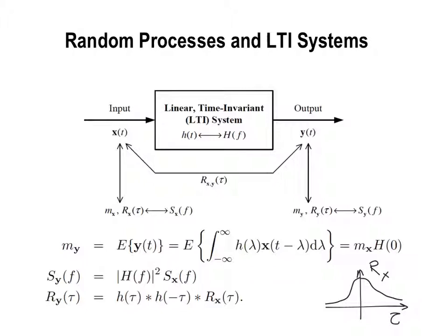You remember when we talked, in the last lecture, about the properties of Rx of tau. We said the peak value is at 0, and then any other value is going to be less than that peak or equal. And if it reaches this value again, it must be periodic. You remember? It will reach it every same duration, right? So the important part that we care about is the fact that this is the highest, and any other one is either equal to or less than that point at tau equals 0, right? Okay. So this is in time perspective.